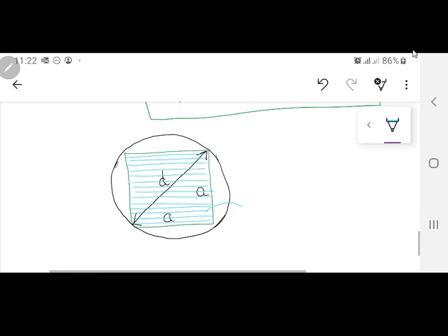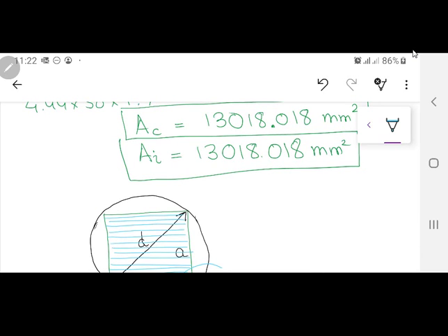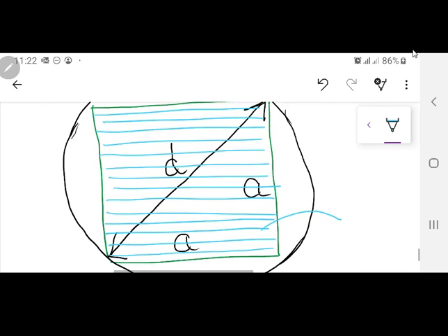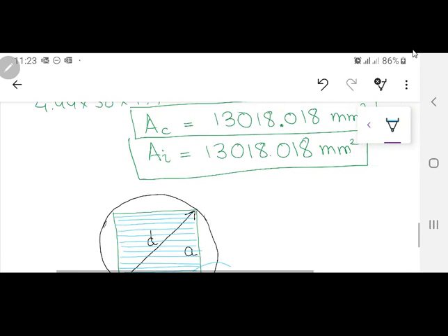Now, since the area you have been given or you have calculated is the net iron area, but when you are going to stack laminations together, there is going to be a resin applied in between them. If you are a very good manufacturer, you will spray that silicone resin with some sprayer. Or if you have a very bad laborer or worker over there, he will use that brush and apply that insulated resin. And if it is very thick, when you are going to stack the laminations together, the area is going to be large.